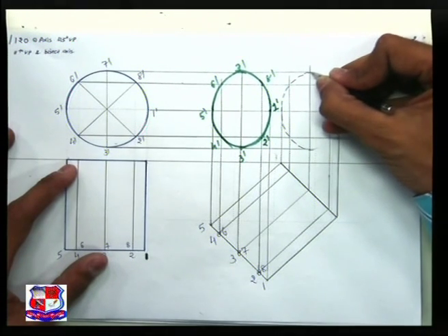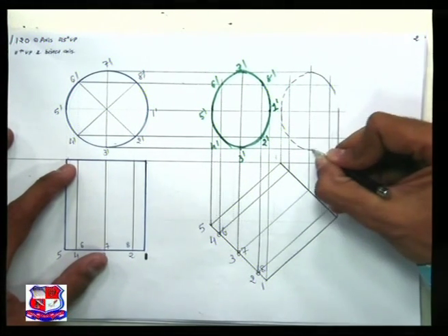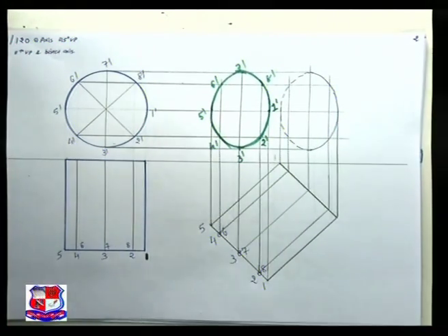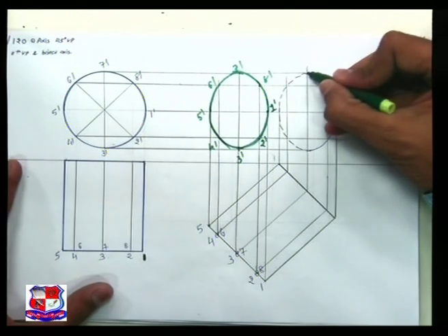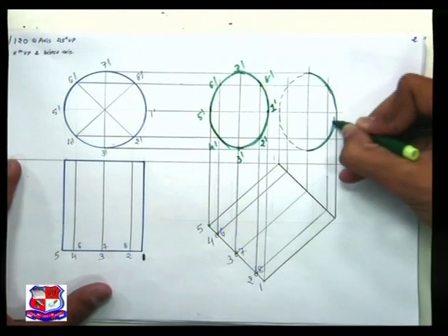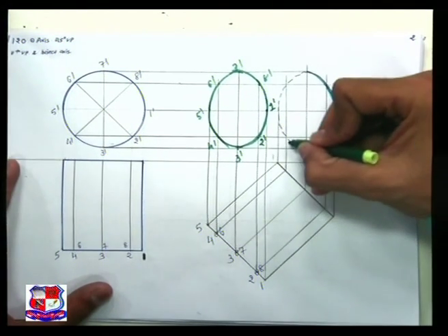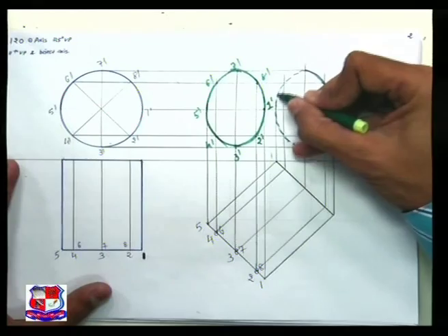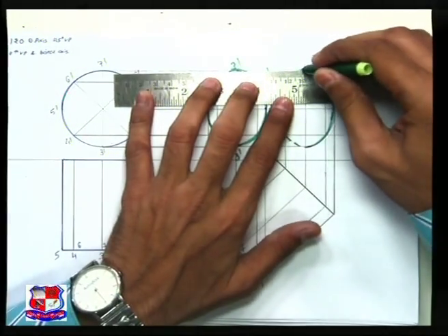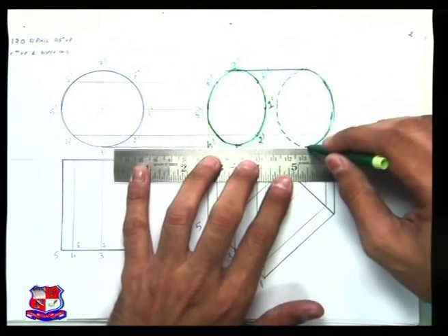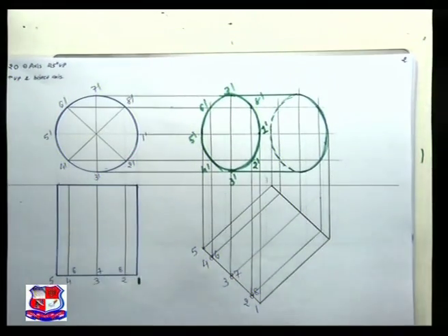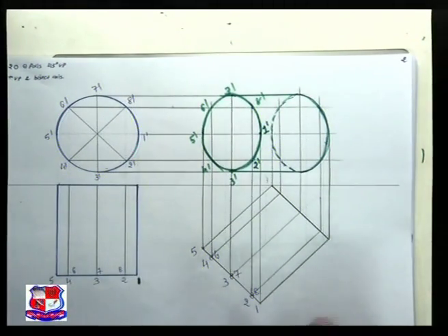And as this is an outside diameter, outside line, it should be represented by the solid line, as we have drawn with the green. Use the same color for consistency, like this, and this is the dotted line, and the slant edges, straight edges tangent to both these ellipses should be drawn over here. So this is the solid, the position of the solid is drawn.